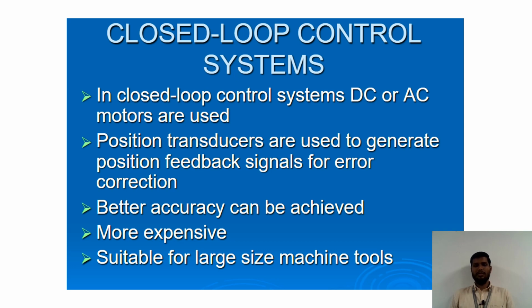The closed loop machine tool controls have a motion control with a provision of feedback, which can be used for accurately controlling the drive system by comparing it with the input information until the required or desired position is achieved. In most of the cases, the feedback is measured by the monitoring devices determining the drive displacement. Various sensors are used to measure particular quantity and give signals to the MCU to compare it and take required corrections.